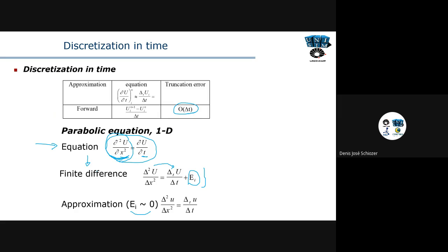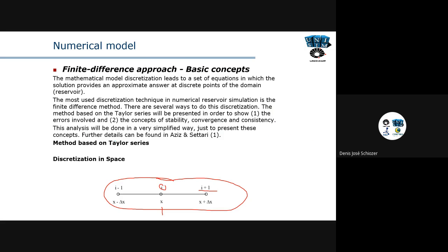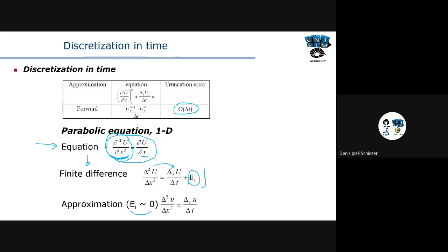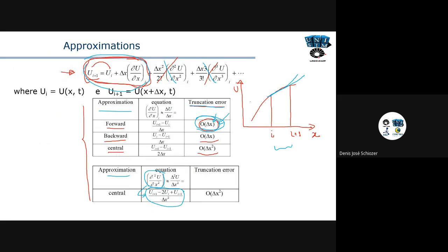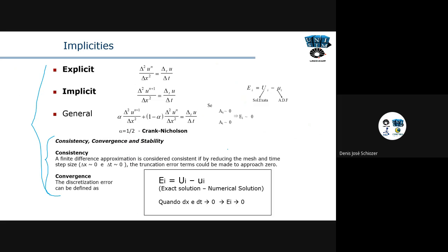The most common thing that they do is, if you have convergence problems, they decrease the size of the time step. If we decrease the size of the time step, we are decreasing the errors, we are decreasing this variance here. So we cut the time step in half and we solve again, and so on. We are going to see some details about that probably next class or the other.